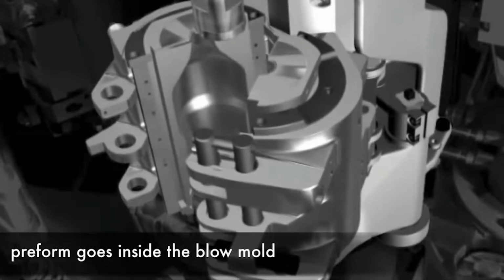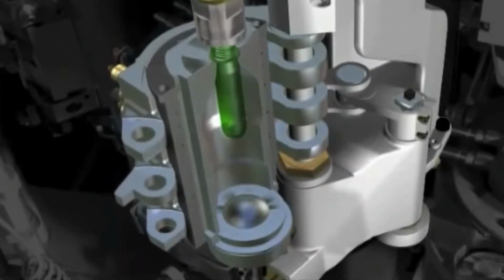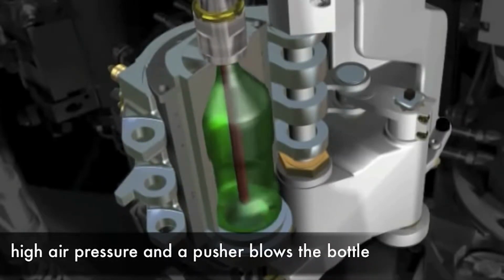A long needle pushes up through the preform, which is suspended with the screw end facing upwards. The needle stretches the preform towards the bottom of the mold and simultaneously blasts enough pressurized air into the preform to force it against the sides of the mold. This stretch blow molding process must happen quickly to maintain the bottle's integrity and consistent shape.